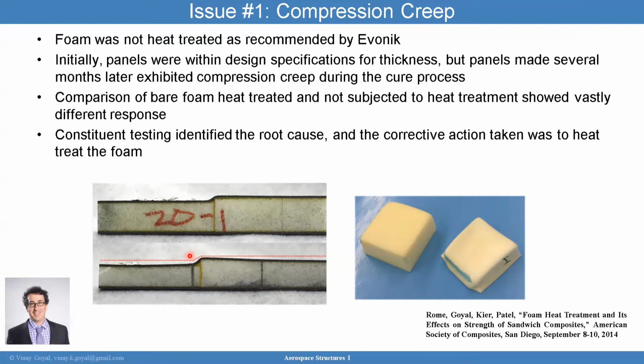This is something that occurs during the cure process of a foam core. Basically, if it's under high temperature for a long time, it will creep. Now, there's a way to avoid that, and that's by doing a heat treatment. And this is the lesson learned: we missed that, or we didn't realize how important it was. So we went back, we realized this, and we said, okay, let's go fix this.